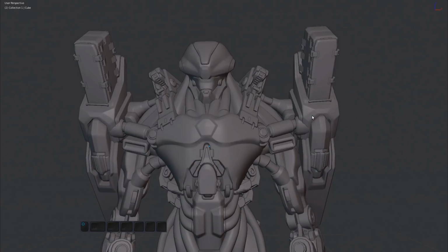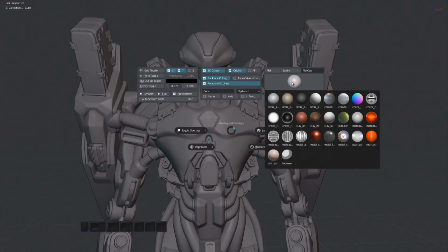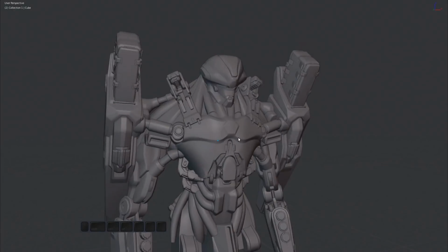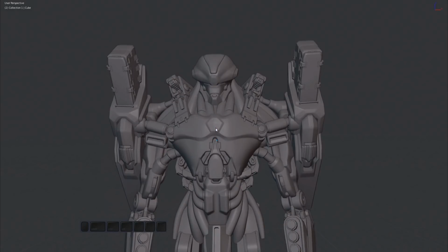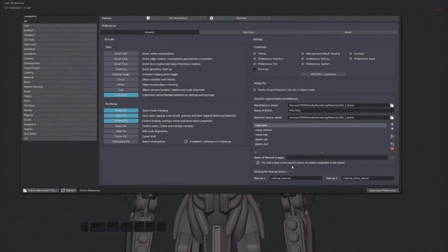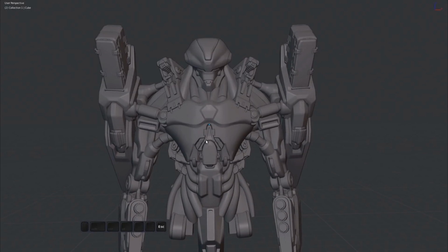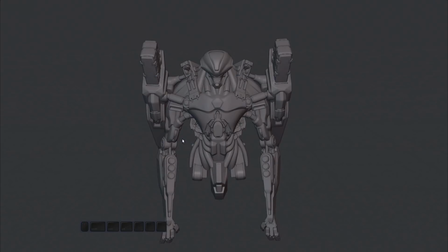With matcap shading, the matcap switch tool appears. It allows you to quickly switch between two matcaps, which you can determine in the preferences. So far, we've only been in solid shading, of course. In solid shading, you can use the pie button on the left side to toggle overlays on and off. Grids, wires, selection highlights, all of it at once.